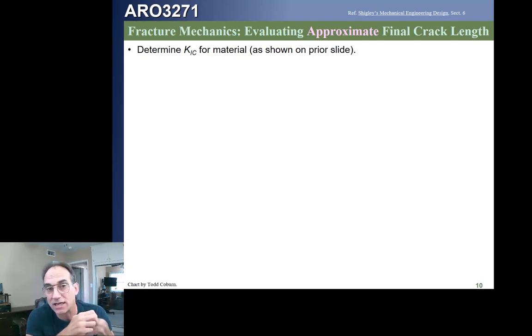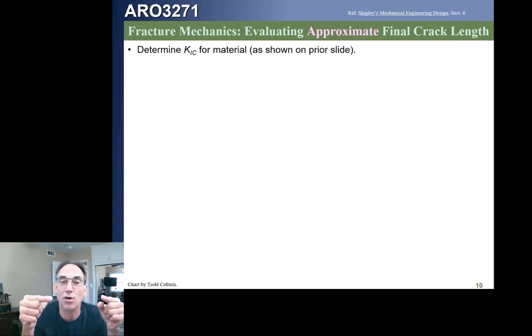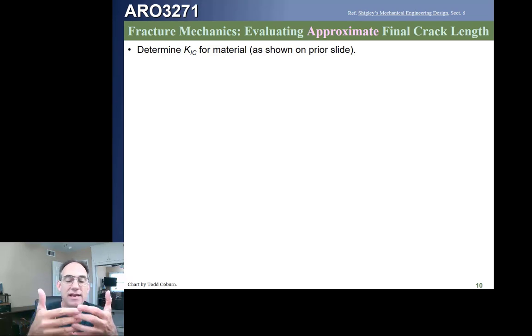Now remember, with fracture mechanics, we're calculating a stress intensity, but we're not calculating a stress concentration factor. We're using that far-field stress. So regardless of how that crack grows, we're using the same maximum stress in the part. All we're doing is coming up with new stress intensities based on the shape and size of our crack. Once we have a maximum stress, we continue to use that maximum stress in our calculations. Since we just found that fast fracture doesn't occur for a crack of a certain size, now we're going to ask, at what size will the crack actually cause fast fracture?